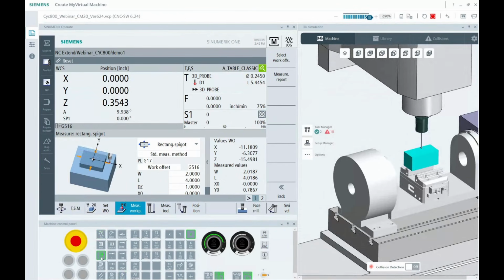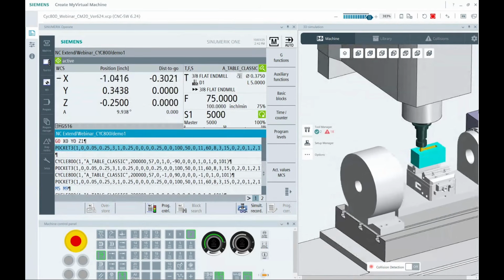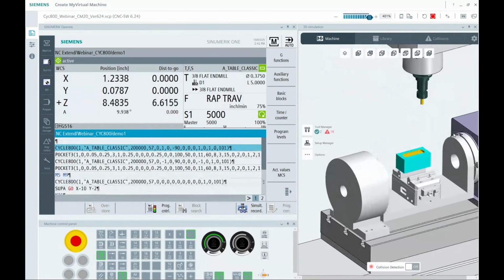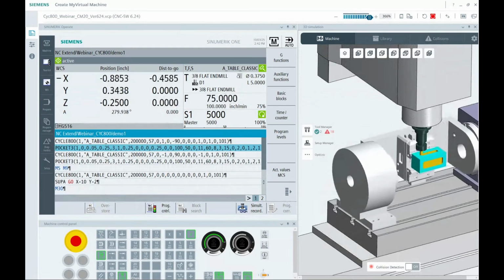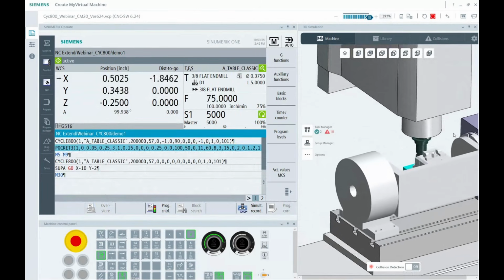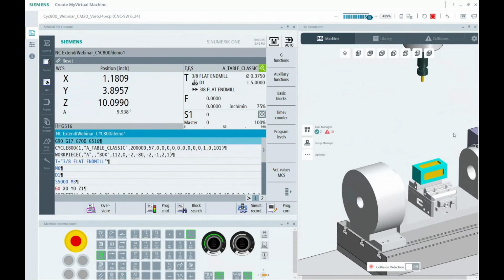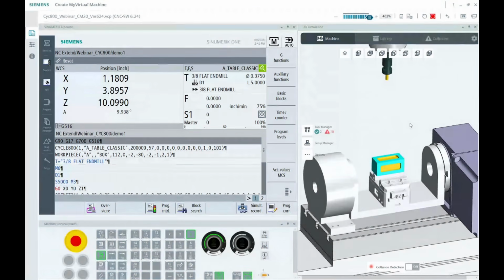I can still go straight back to my part program, cycle start, and this would never work had I not been using dynamic fixture offsets with Cycle800. There you go. That is why we do it right there. It gives me total freedom, lets the machine manage the center line of the part. I don't have to try to position things exactly where they were in my CAM system, right? I have complete control over where this is right on the shop floor.